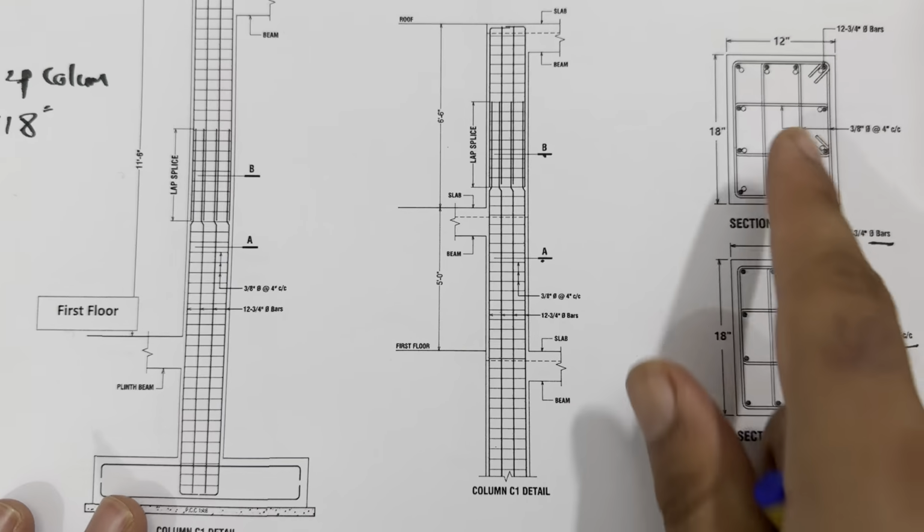So next, guys, you can see clearly the section A. For the section A, we are using this section, and for the section B, we are using this plan, okay? So the steel reinforcement, everything is the same, but here you can see we have two bars. You can see the empty bar, which can show you the lapping length. So here you can see clearly. The lap splice, guys, you can get from the value, as I discussed in many videos, from 40 to 60D. You can use, where D is the dia of the steel rod.